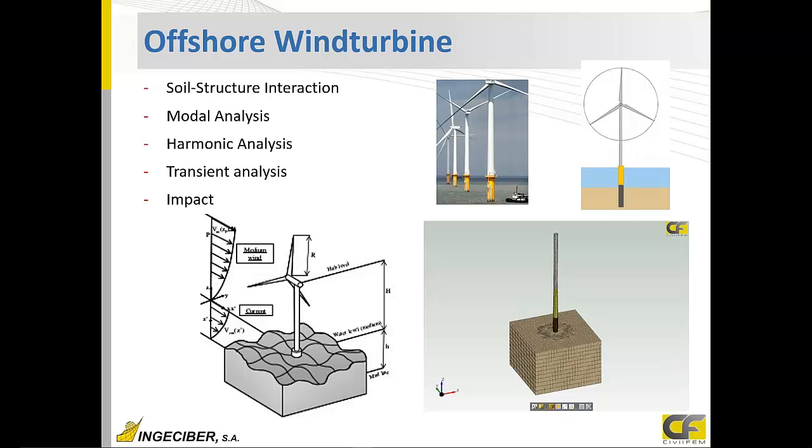We have wind loads, here you can see wind loads on the wind turbine. Also, this sort of model will have waves, which are also dynamic. And it's very important also to model the soil. Frequencies depend on the soil around this monopile.